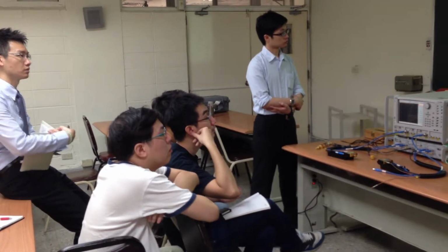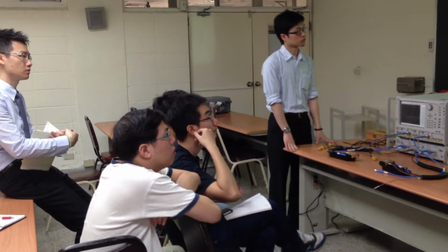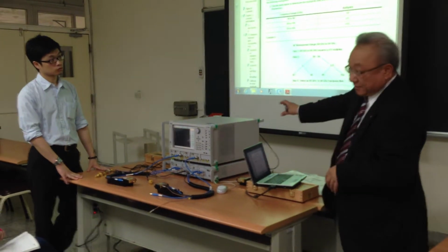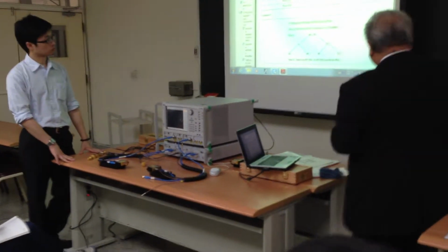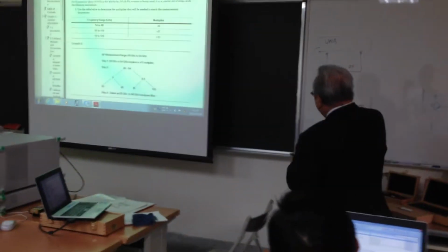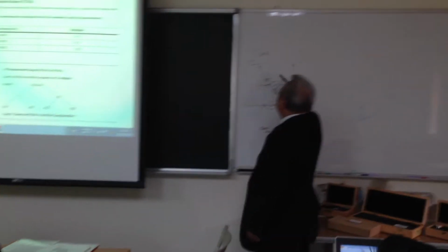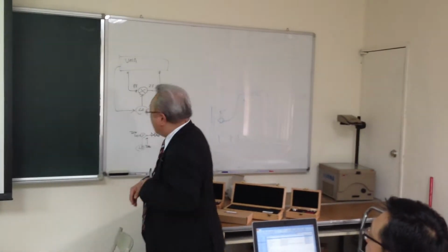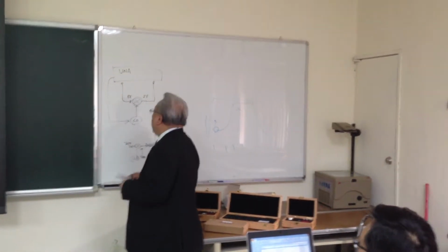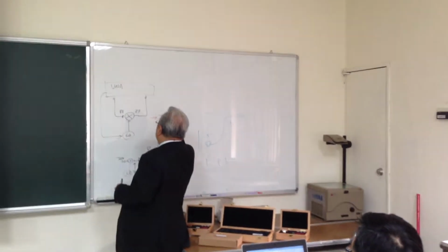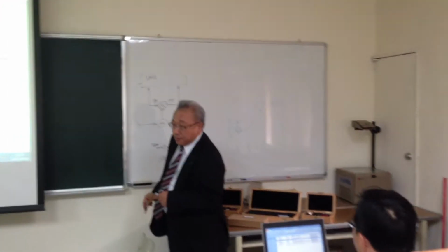Mixer NF measurement we can do, but currently we do not have a mixer NF measurement user interface in a VNA, so we measure it manually. First, we will make a measurement of the conversion gain. The conversion gain is extracted only to a text file, not an S2P file.